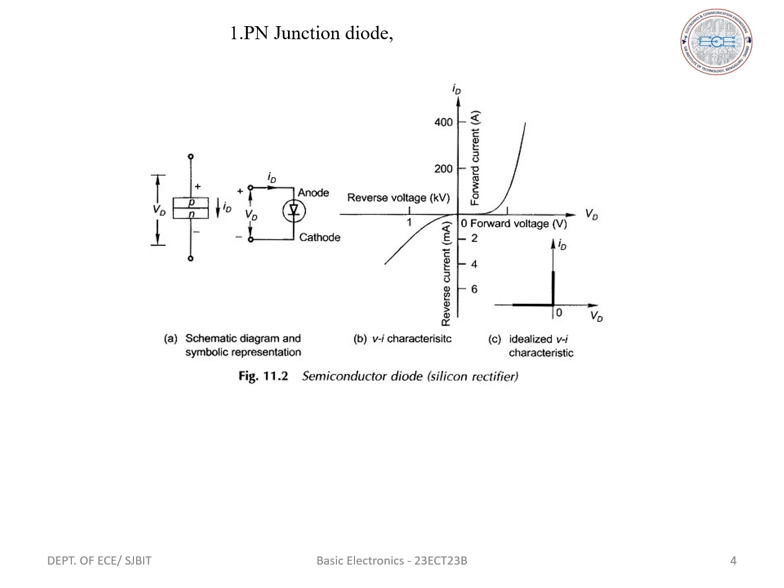When the external voltage is not applied to the diode, the PN junction continues to be in the state of equilibrium. Therefore, there is no current flowing through it. To make the current flow, it is necessary to bias the diode. The biasing can be of two types: the first is forward bias and the second is reverse bias. First, we'll consider forward biasing of a diode.